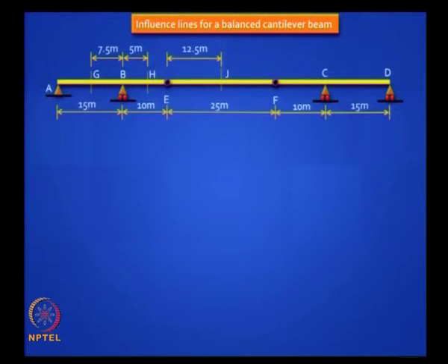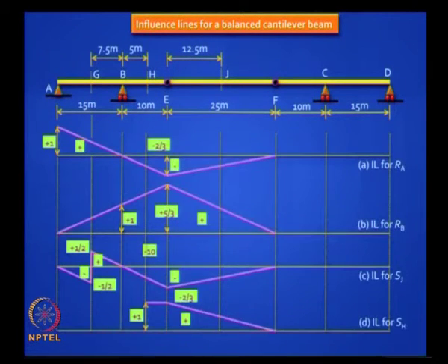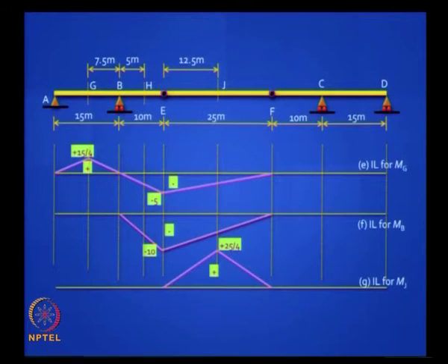So you should follow a sign convention, but you can also try drawing and getting the support reaction at A and B. Can you try that? Influence line for support reaction at A and B and so on. It is very easy, you remove the reaction at A and you lift it up. How will this move? We have done this earlier, you get a series of lines, they are very easy to do, they are all straight lines, and once you catch one value you can catch the rest of it. So I would like you to recall what we did.